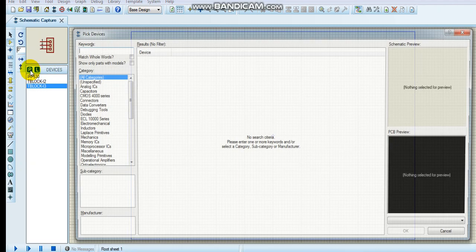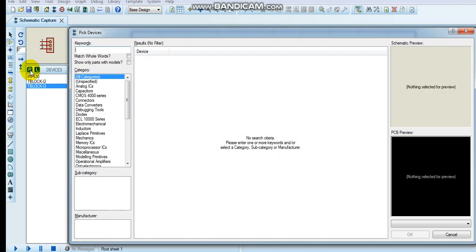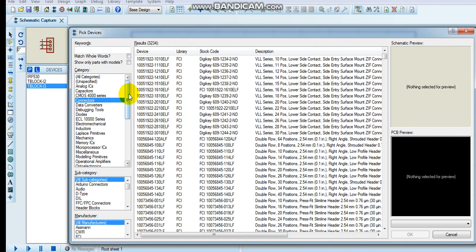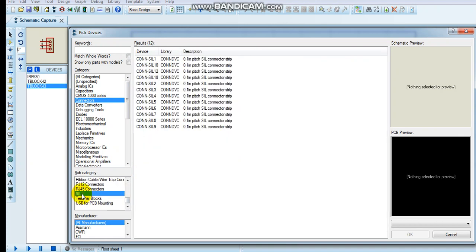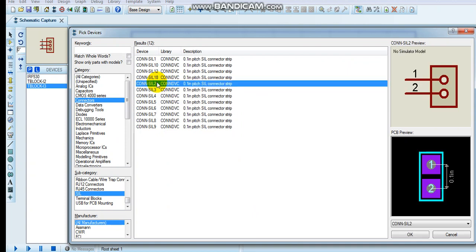Another thing, because I will use the switch with the signal, so this another type is named for the contactors. It's named SIL. Yeah, the contactor will be named SIL. I can find it easily here because I need to use this one as the switch signal. We'll use it later with the gate driver circuit.